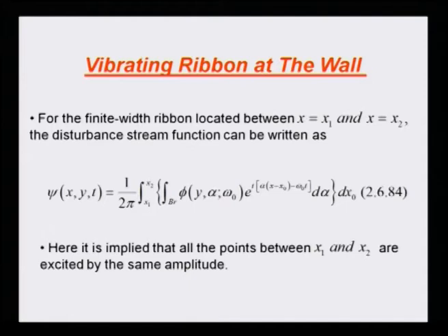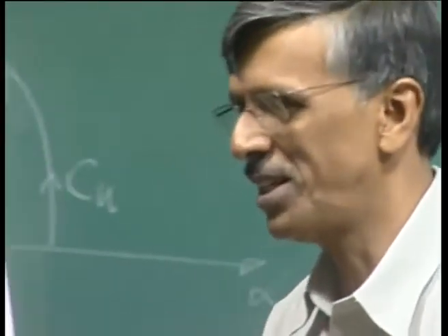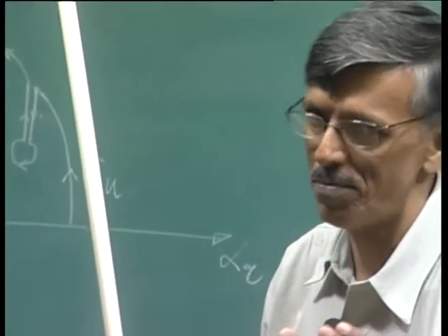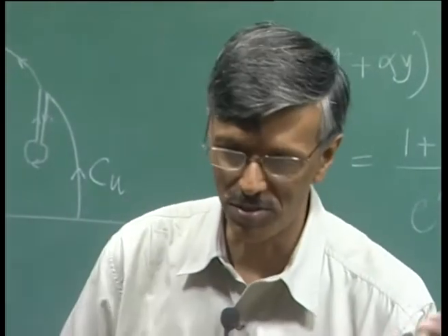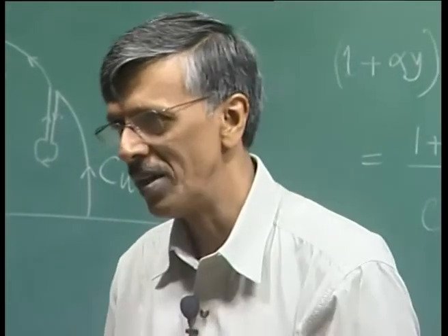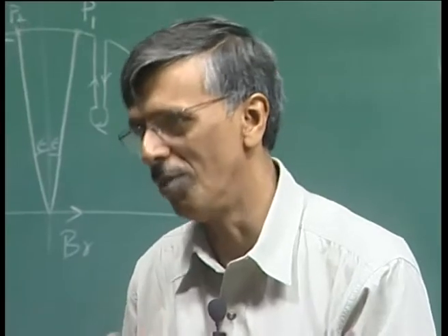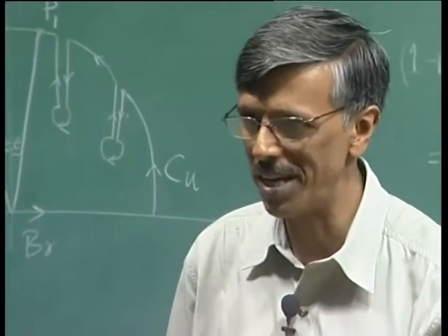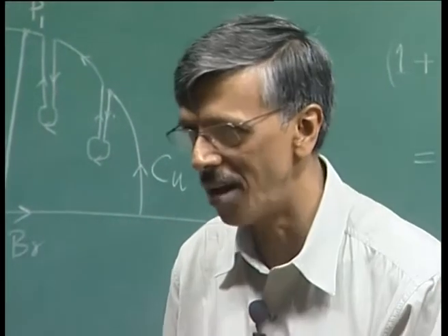Analytically, it looks neat, but if I tell you to go ahead and try to do it for the solution of the Navier-Stokes equation, you will sweat. Why? Because of those discontinuities at the end of the strip. At the end of the strip, you will have 0 and then a finite value, and that will excite all possible alphas, and numerically that's a disaster story.